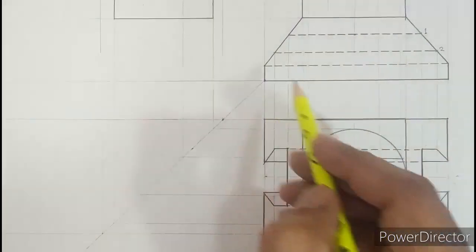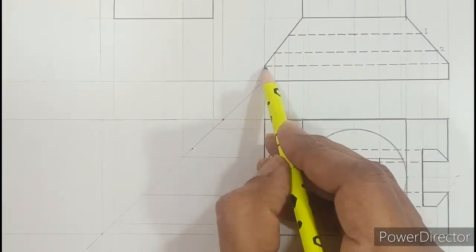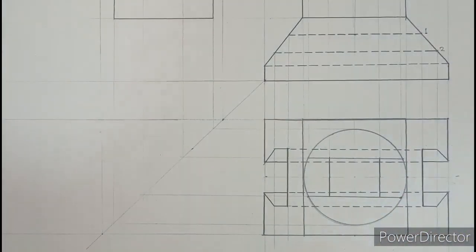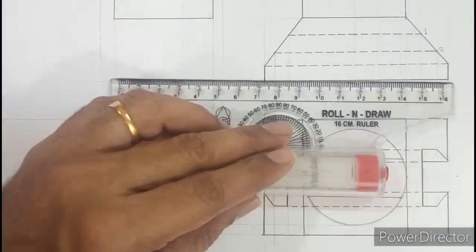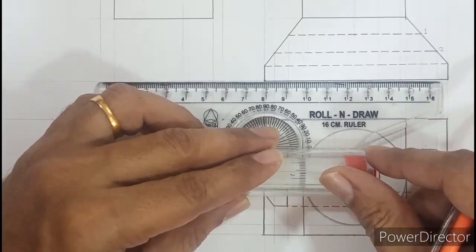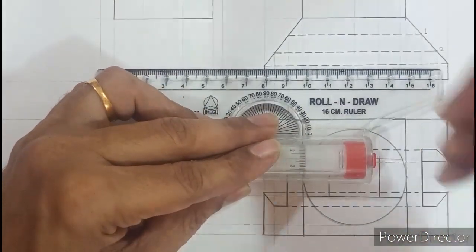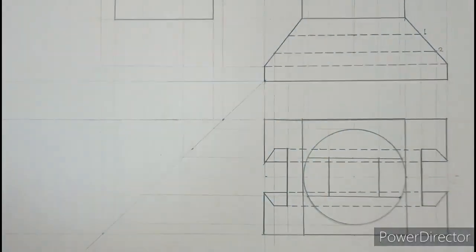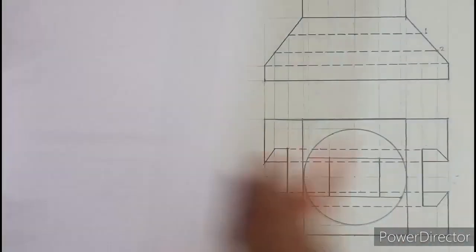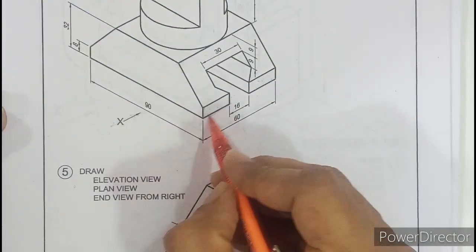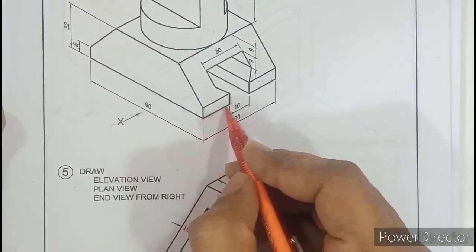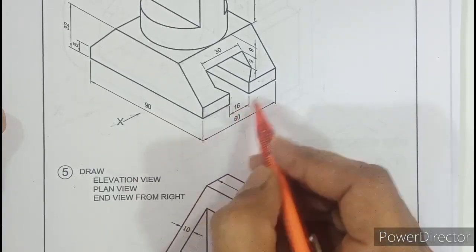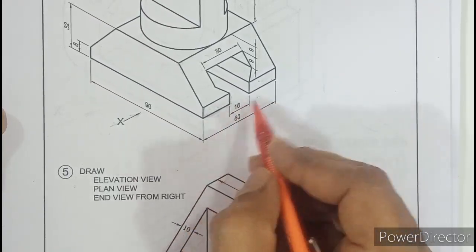If you look at the diagram, that 8 mm is over here. This is that same 8 millimeter we are talking about. We need to project that 8 millimeter in the side view. So the correct word is project. From here we'll project a light line in the side view like this. Apart from that, we should also know the width of this. It can be easily found out by subtracting 16 from 60 and dividing by 2, but that will not serve the purpose of learning orthographic.